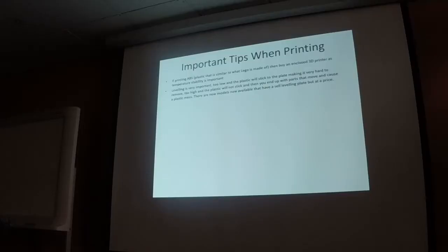Leveling is very important. Take your time getting your leveling done right first. Generally, once you've done your leveling, you don't have to worry about it pretty much after that. Place the printer on a solid platform that does not shake and move when the printer is working, because if it's flimsy and the head's moving around, the whole thing's moving around, and you can cause yourself some problems when it comes to printing. We're talking 0.01, 0.02 of a millimetre. Very small amounts that these things print at.